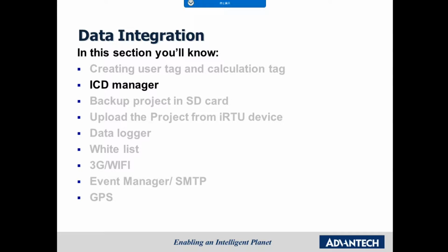ICD Manager is a communication monitoring unit which can diagnose both LAN port and serial port. For LAN port, ICD Manager will acquire the network status information output by the network card to test its current status. For serial port, ICD Manager will acquire the communication signals on the physical layer of the serial port to obtain the related information, including its active status and the response time of the data package on the serial port.